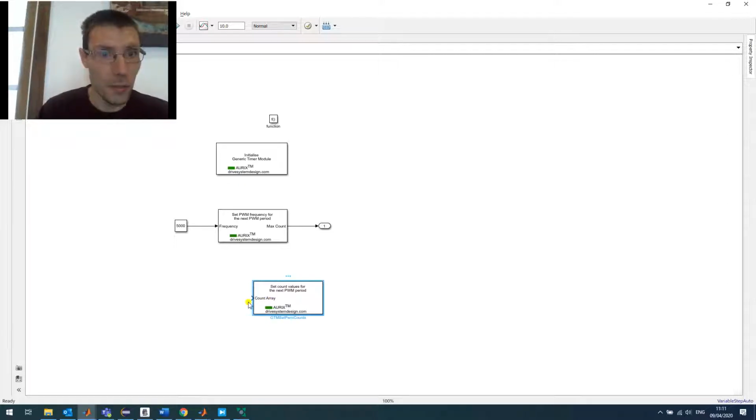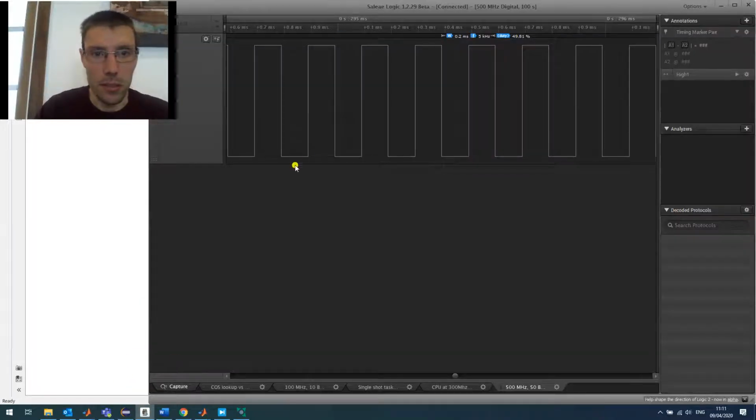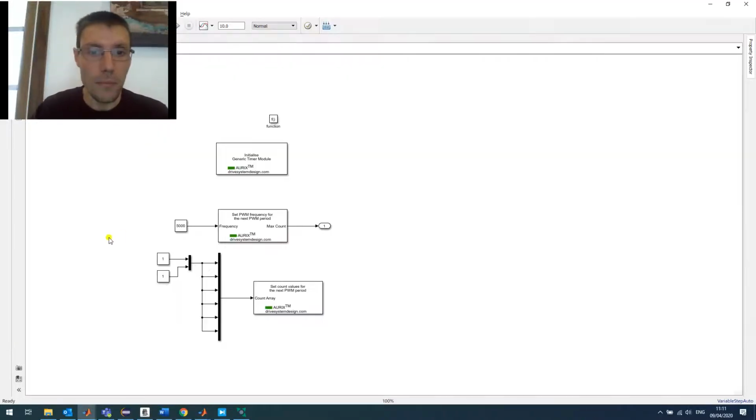And here you have the block that we use to update the PWM duties. We have 6 switches, so you have 6 inputs to the function, and then for each switch you have the T on and T off time. So you select T on, T off, so that you have full control over your signal. So that's it. Once again, very easy. It's all set up already.